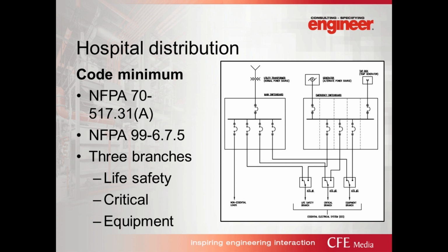Now, we'll mention there is an instance in the code where a hospital is not required to have the 3 branches subdivided by transfer switch. One transfer switch is permitted to serve more than one branch, or all 3 for that matter, but only for systems that are 150 kVA or smaller.